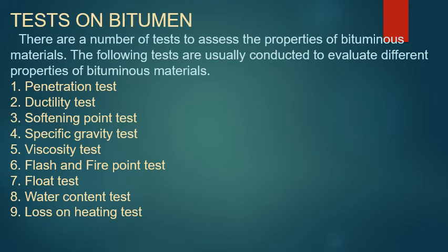And the next is susceptibility and durability of bitumen under prevailing environmental conditions should be evaluated throughout its period of serviceable life. Means of pavement, if you are designing for say 10 years, during those 10 years, the environmental conditions which the pavement is undergoing need to be evaluated and considered.